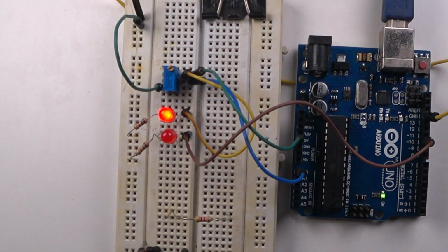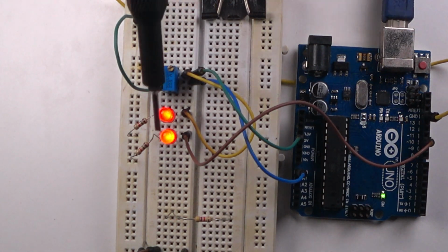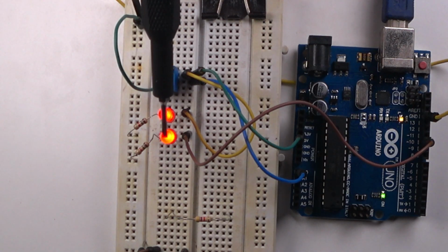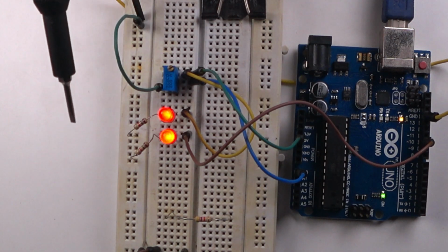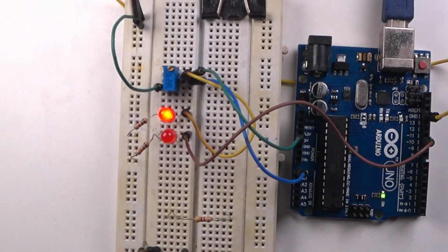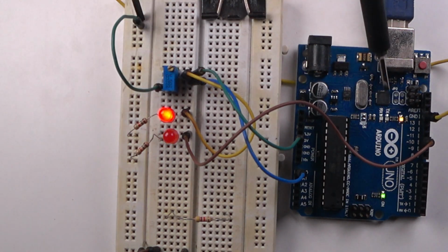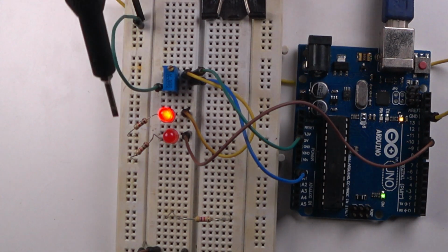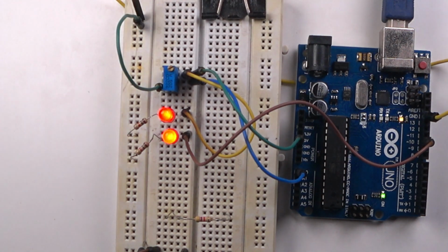Okay, a little experiment. Here we have an Arduino and two LEDs. One of them is constant on, the other one is blinking. The constant on LED is connected to 5 volt, then to this resistor to the ground. The blinking LED is currently connected to pin number 10, which is a PWM pin. Same resistor and then the ground. The little blue box here is a trimmer. It is a resistor whose resistance value I can configure based on a setting of this screw.